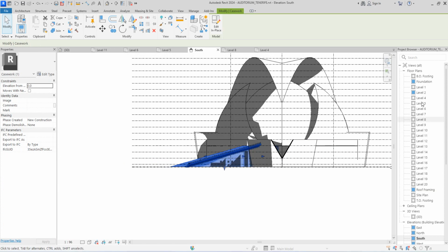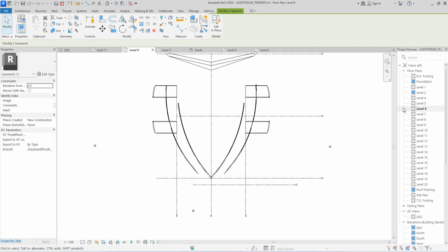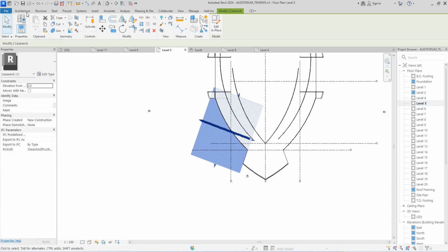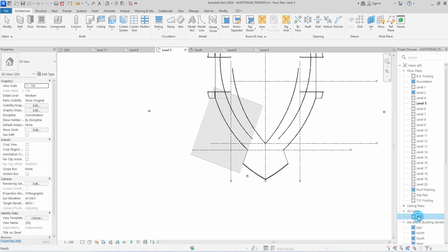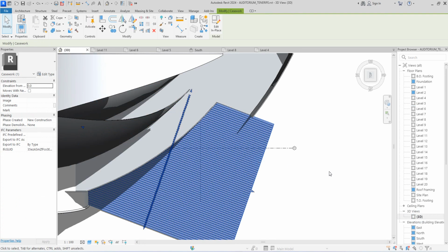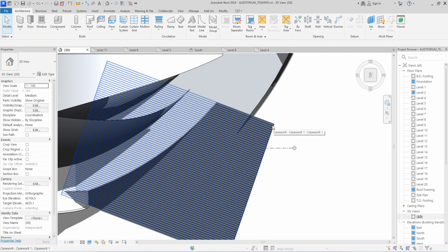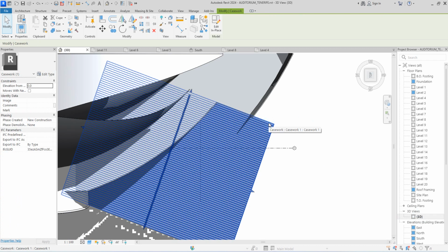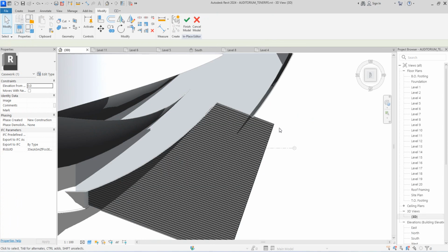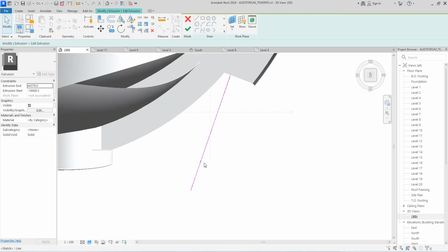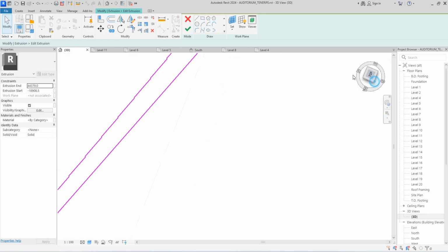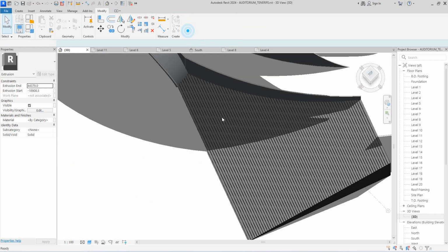We select it back. We go back to elevation, system here. So what you do, select this one and say void extrusion. At which level do we do the work? So that is where the problem starts from. So select this one. The elevation is at level 0. So you use a reference plane to do that. Then how do we do it? Say edit in place, then edit again, edit visibility. So this is where you do your visibility editing, everything. So you click finish.